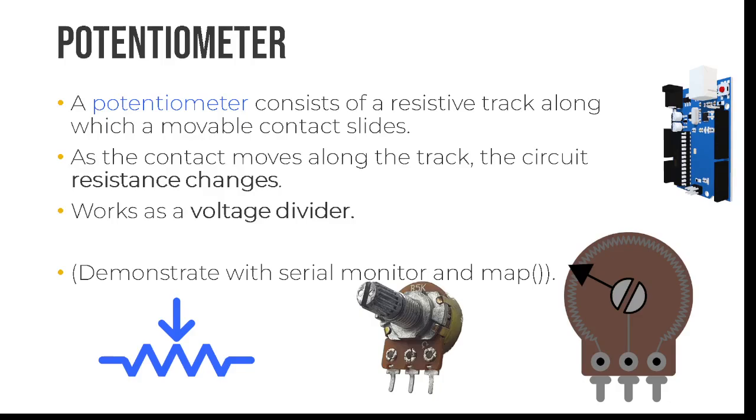They are a resistance whose value we can change, right? It has a fixed value. For example, this is a 5K one. You can have a 100K, whatever, right? This is a schematic of its internals. It's just a resistance that is connecting these two terminals, right? So, for example, if this is a 10K potentiometer, what do I measure if I connect the multimeter here and here? 10K, perfect.